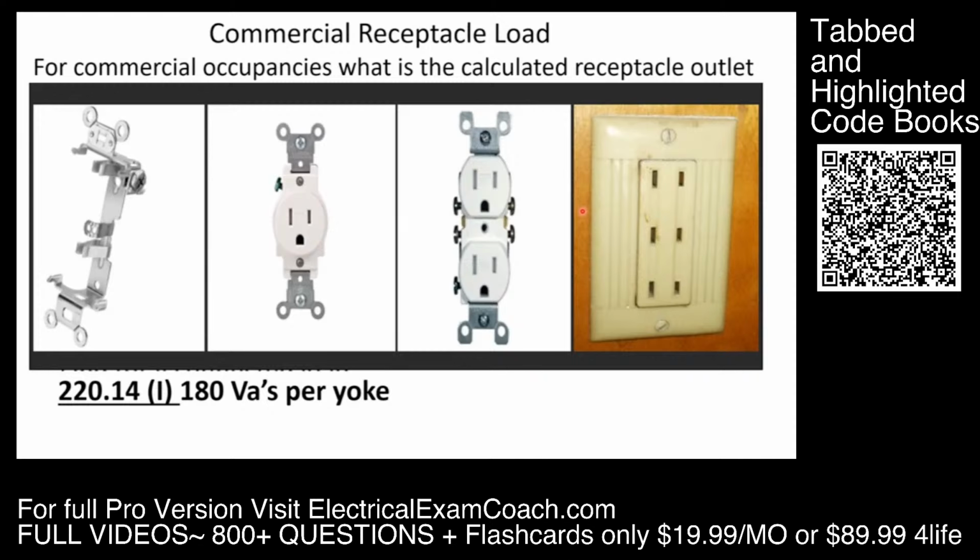So if I have a single gang box, it's 180 VAs. If I have a 2 gang box and they're both containing receptacles on each side, it would count as 180 VAs per gang, and so on and so forth as you went to 3 and 4 gangs. Anytime you're dealing with a device strap, whether it has 1, 2, or 3 receptacles on it, it's 180 VAs per yoke. Now, let's check for demand factors.